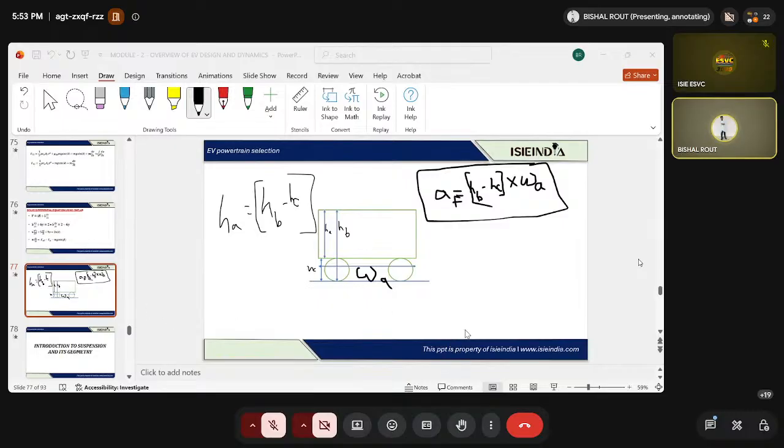Let me see. Let us suppose from 0, 31.11. If my speed is 25 kilometer per hour, what must be the possible torque? Because we had not calculated over here. Let me see whether it can calculate or not. If I take it for 25 kilometer per hour and apply it, you can see this is the torque, 8.036, which is the torque that is created. So it can apply the value even if you had not calculated or plotted it inside a lookup table,